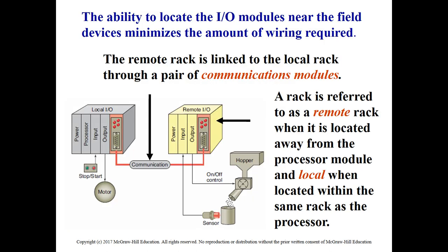In the case of a big PLC system or a super PLC system, we may need to use a lot of input output devices, a lot of input output modules. So in that case, instead of implementing all the input output interfaces in the control room, beside the main server that controls the unit or the process with the processor, we are going to place some of these modules near the process in the field.